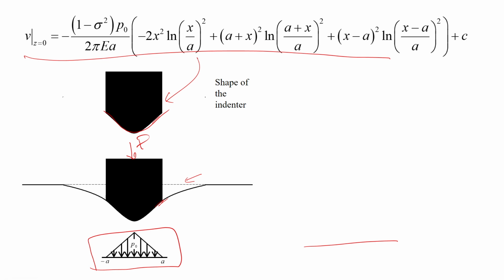So, I have first brought it in contact, with load, and now let us say I am trying to separate it. In that case, I am looking for an indenter shape that will give rise to normal load once again. It will look something like this, the load distribution. Let us say the maximum load is at x equal to 0 here, and then it is something like that. In that particular case, what will be the deformation profile, and following that, what is the indenter shape, basically, that we are looking at.